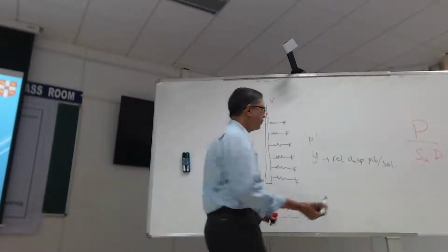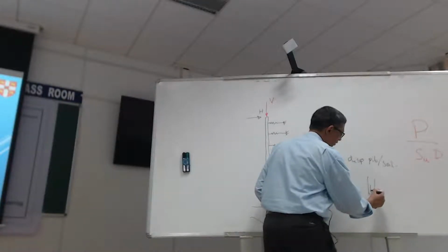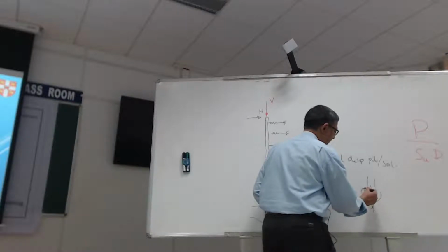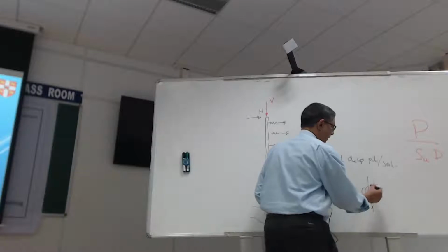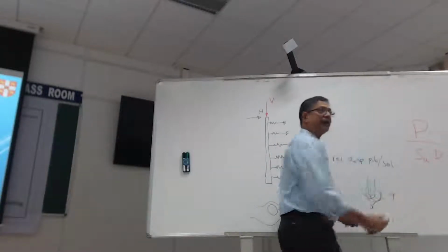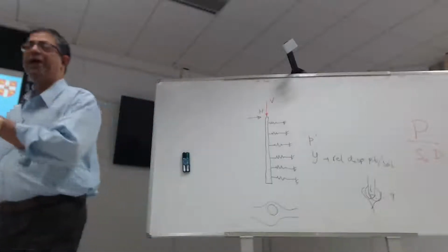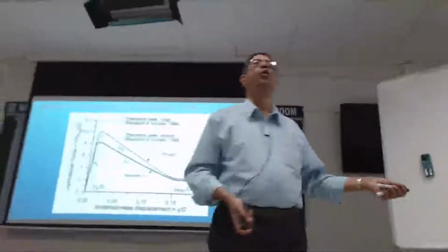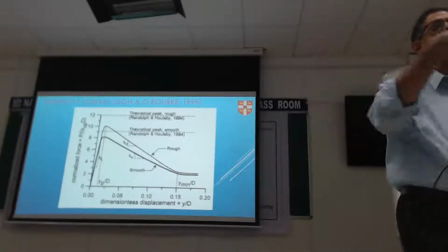And that is going to be same as, so if I take a pile trying to be pushed in, the soil flowing along it. And we know this mechanism for that, the deep flow mechanism, and that is again 9, right? Roughly 9. So this sits well with the known theory for piles going this way to soil going that way.